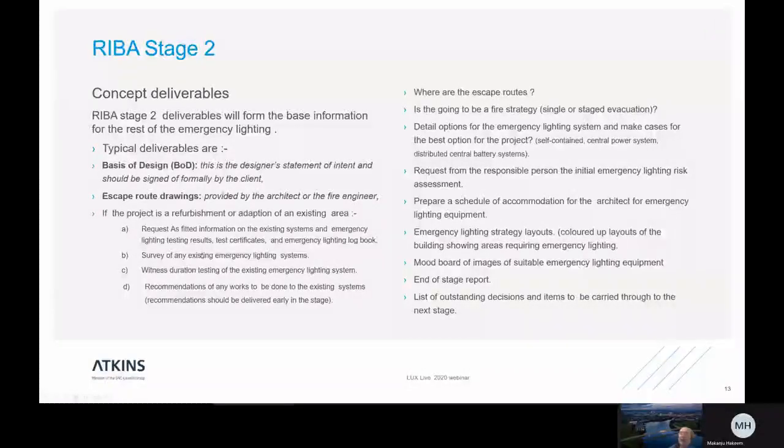So you should also do a duration test, an annual duration test of the emergency lighting, existing emergency lighting, to see that it's working and report on it. So it's a survey and a report, and then put that out there, and that will then tell the client of any additional things that they may need to do in your contract, or they may need to get someone else in to deal with those shortfalls so that your contract and your design works for the whole of the building.